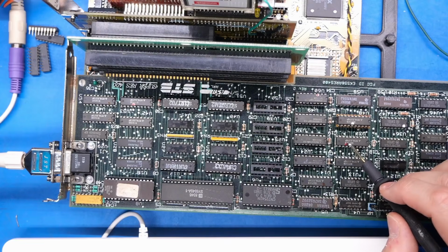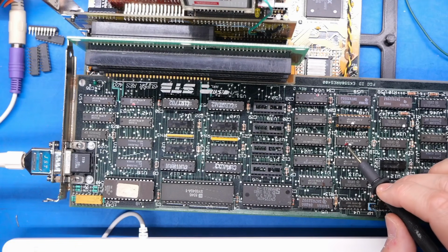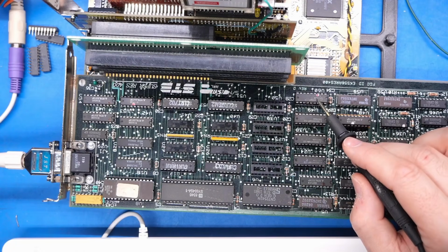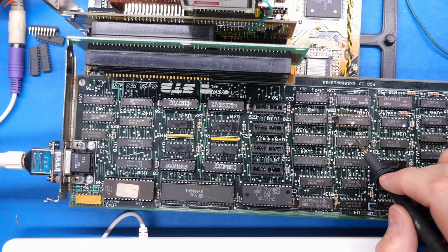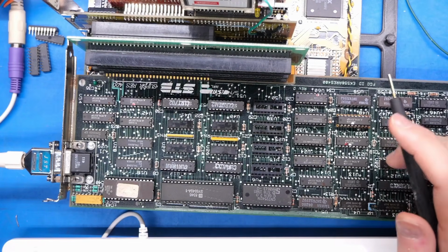This pin here makes its way to this flip-flop right here, with a little white mark, which is an output. And the input to that unit is with the red mark on it, and it's found here on this DRAM chip on one of the data lines. So that could be the issue, but I don't necessarily think so.